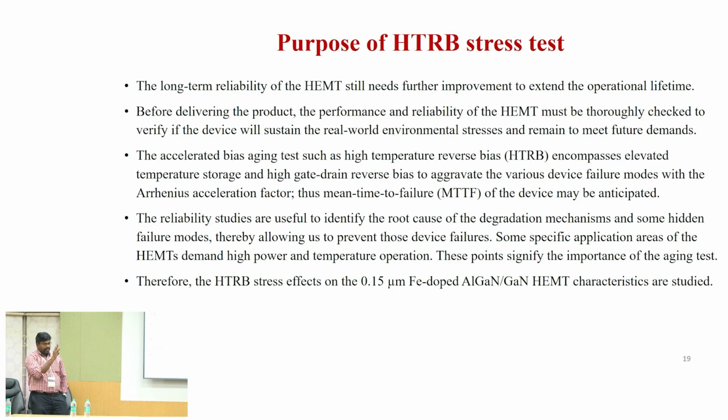So there are some standards like high temperature operating life. You keep the device at operating conditions at high temperature, so that you can estimate the high temperature operating life of your transistor. Similarly, high temperature reverse bias. Even this is much better, because here you are keeping the sample at higher temperature, and at the same time you are giving the reverse bias also.